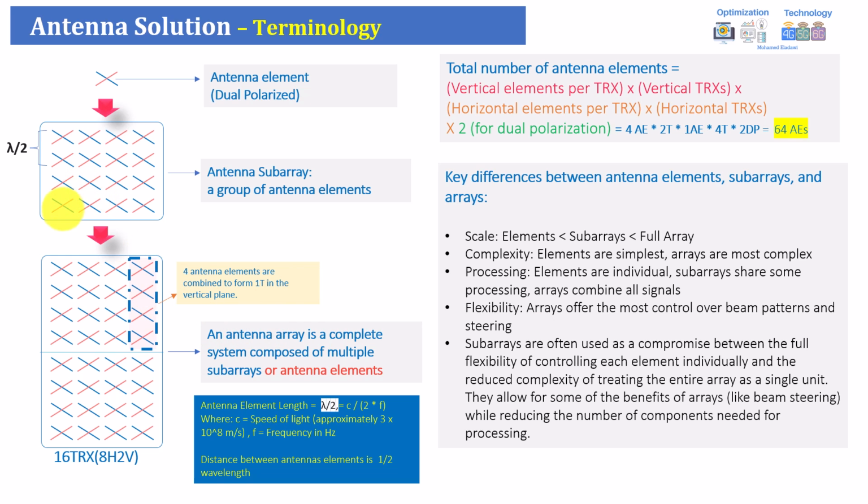One important point to mention, which is something very well known, is that usually between the antenna elements or the antennas in general, you will have half a wavelength between them, and this is based on many studies done before. This will improve your diversity, because the antennas will have distance between them, so they can experience different distances. So this can give some space diversity gain as well.